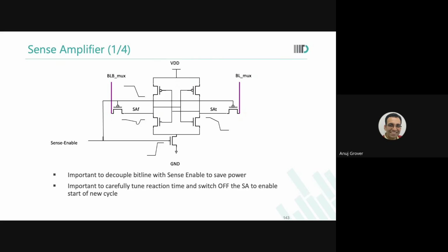So if I have a very short sense amplifier on pulse width, then I would want to go as close to VT as possible, the closer the better. So my offset requirement has increased. Are you able to see this?